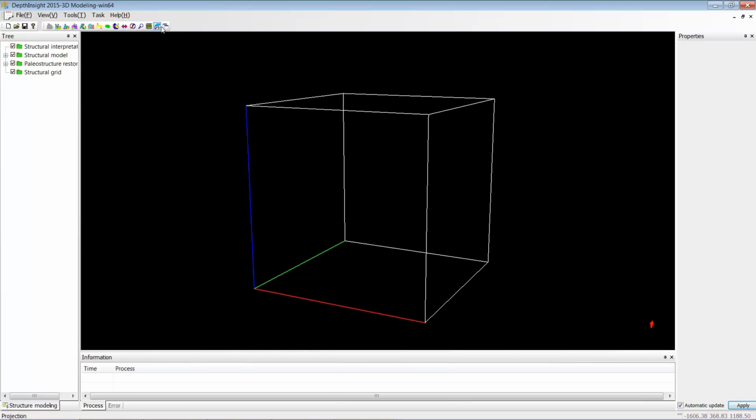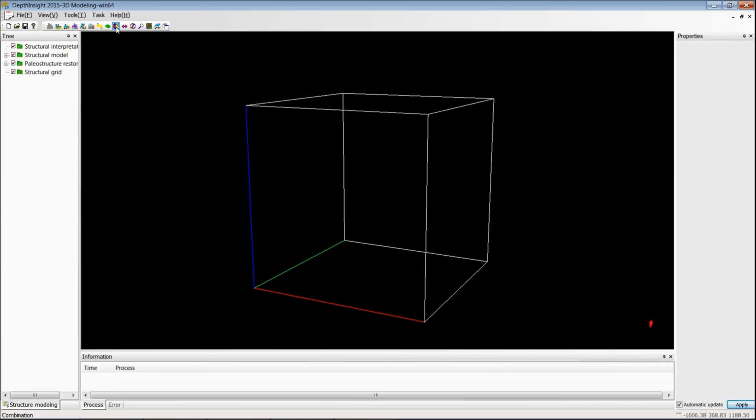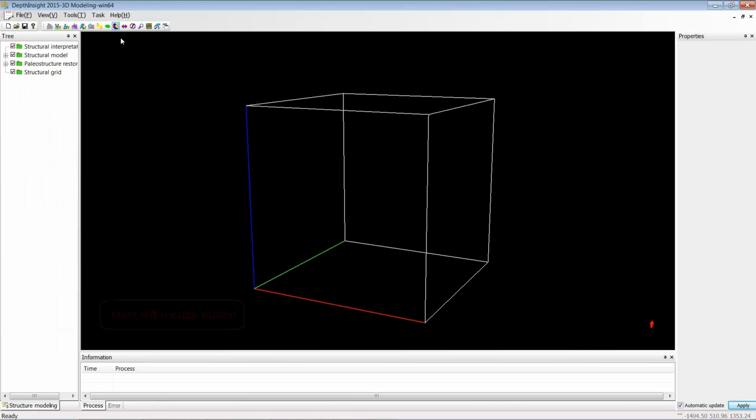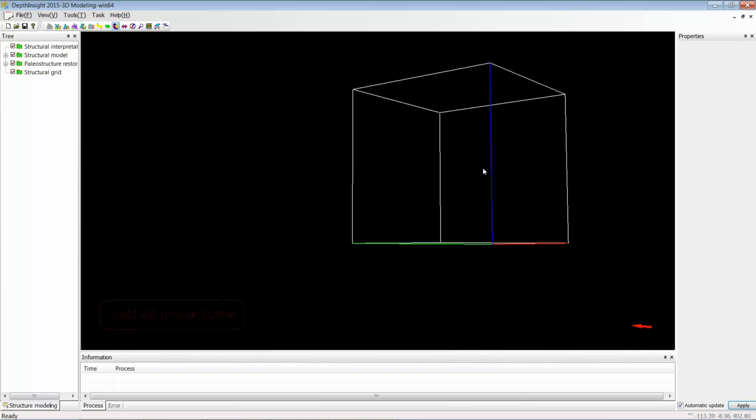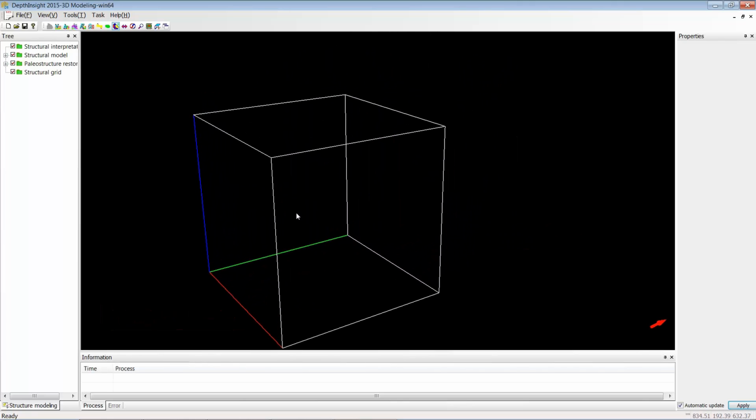The last few buttons are view control buttons, and the most often used button is Combination. Left-click Combination to activate it. Hold the left button and move the mouse. Can rotate the wheel. Press Ctrl and at the same time hold the left mouse button and move the mouse.